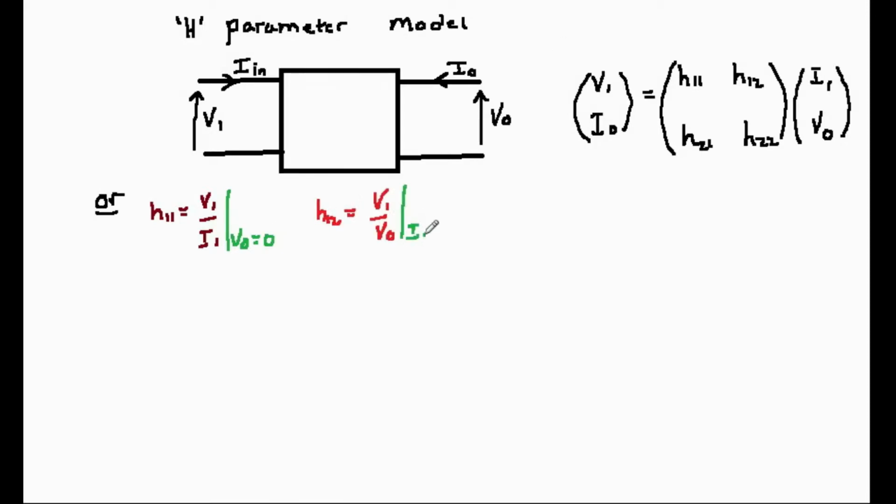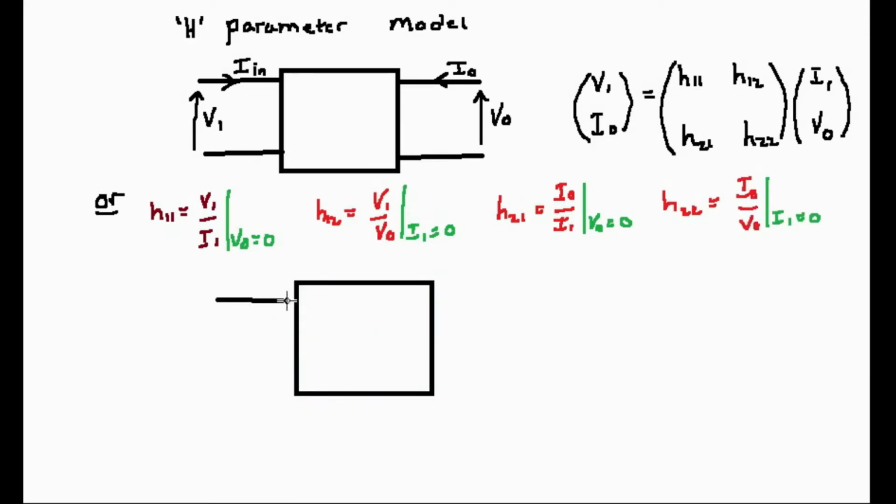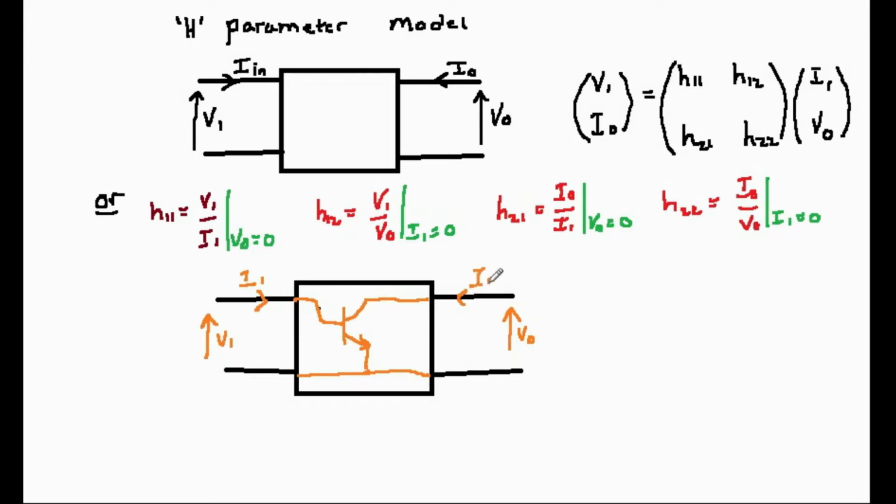The formula is shown on the screen. The matrix is widely used because several of these parameters turn out to be very useful in transistor calculations. We can see this if we put a common emitter transistor into the circuit block and relabel the parameters slightly.